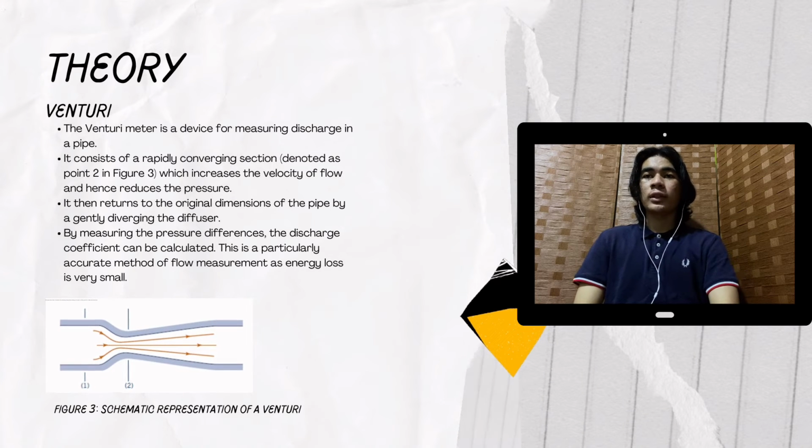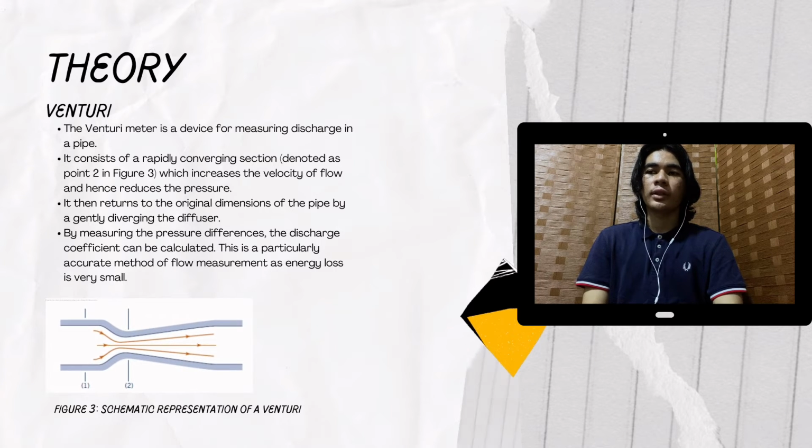Lastly, we will see the venturi. A venturi meter is a device for measuring discharge in a pipe. It consists of a rapidly converging section, denoted as point 2 in Figure 3, which increases the velocity of flow and hence reduces the pressure. It then returns to the original dimension of the pipe by a gently diverging diffuser. By measuring the pressure difference, the discharge coefficient can be calculated.